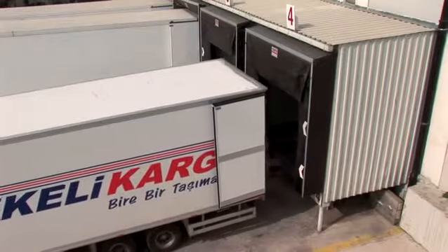If you're offloading directly into the building via a loading dock, you need to make sure that the loading dock is arranged so that it can be adjustable to suit the full range of delivery vehicles that are going to be visiting the site. If you're using refrigerated vehicles, either for collection or distribution, you need to make sure that an electrical outlet is available so that the vehicle can be plugged into it in order to prepare it for deliveries or to keep it operating at the correct temperature during the offloading operation.